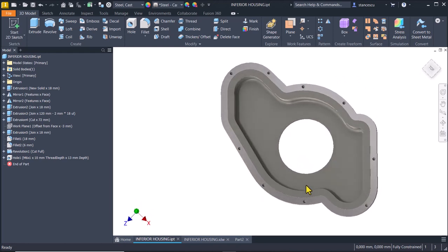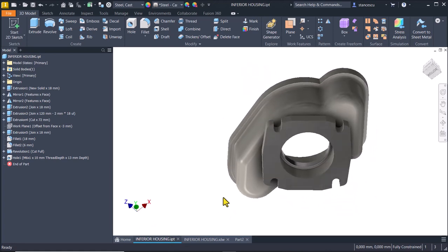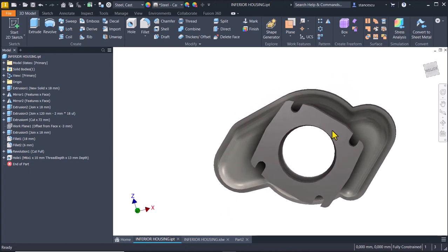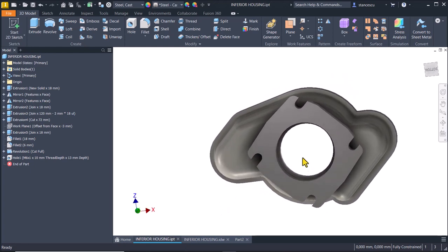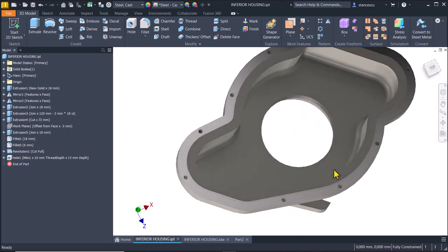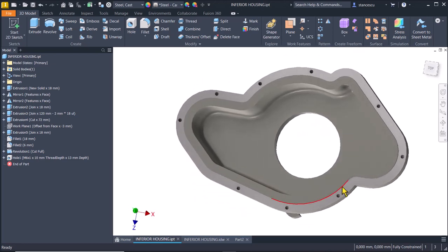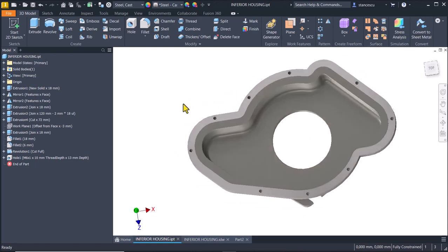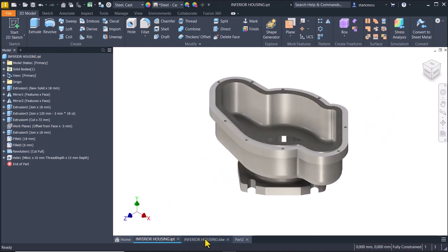We use this position, but in the drawing this is the position. This I create a quarter sketch. In fact that is here. You see a quarter here, and I mirror twice to obtain the plate. Let's start.